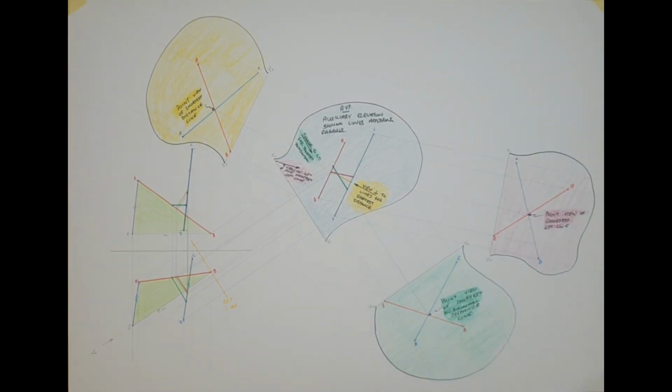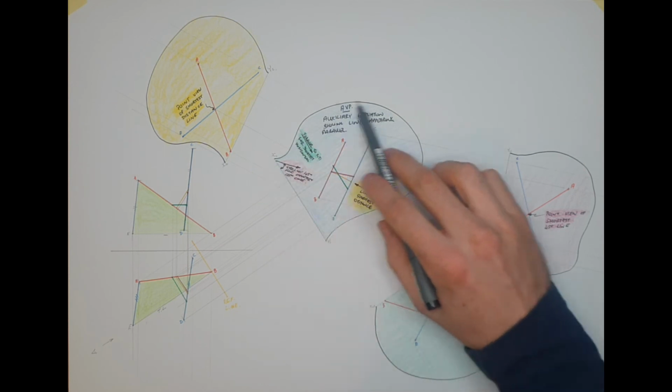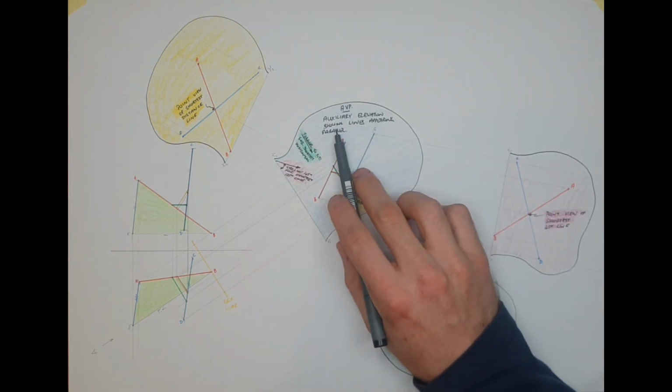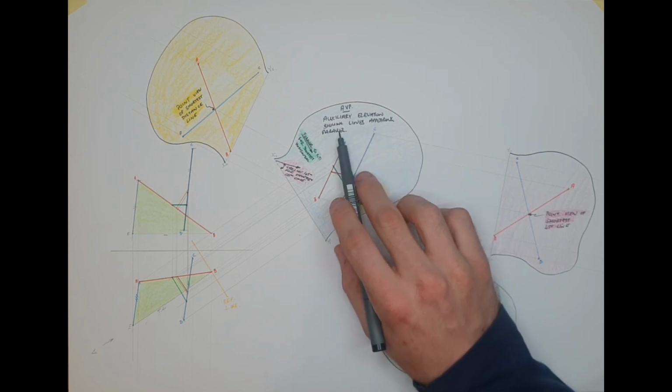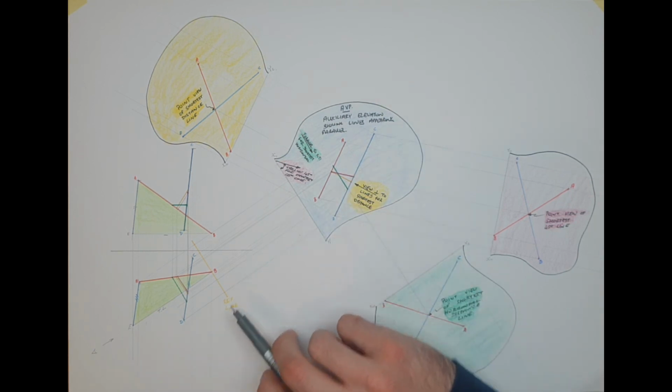Now the little bit of colour is added in there, I think it might help with the fact that there's a multitude of questions answered here all in one. Hopefully the bit of colour and label will help with that. I've just labelled here that this is the AVP, the auxiliary vertical plane, in blue. The auxiliary elevation shows the lines appearing parallel. So that's the main purpose of that view.